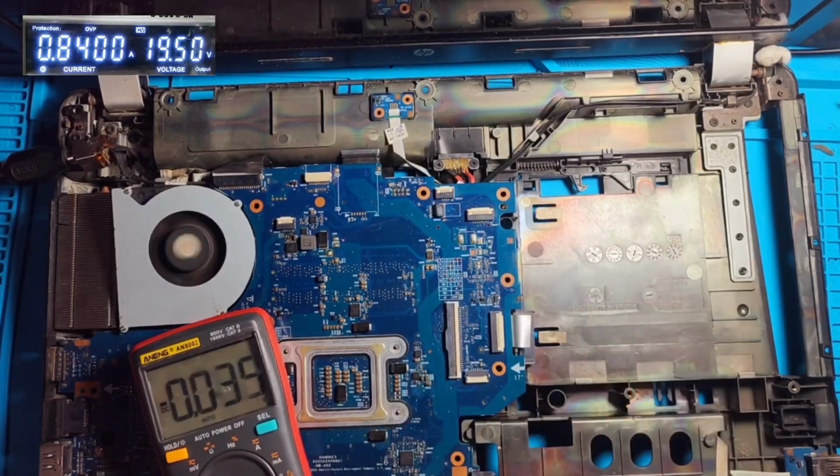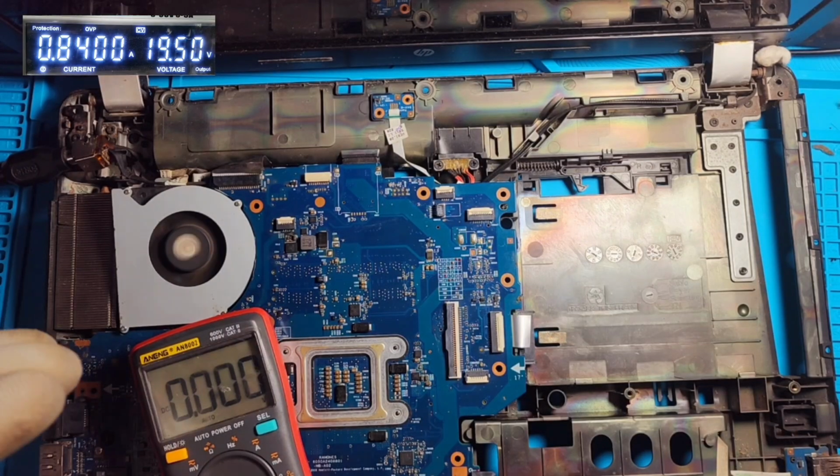So let me go from the basic checkups, from the diode checks. Then I can go straight to oscilloscope testing the voltage rise in the sequence, so that I can capture the first sequence of the voltage rise when the board turns on, so that we can identify the problem that is causing no display.